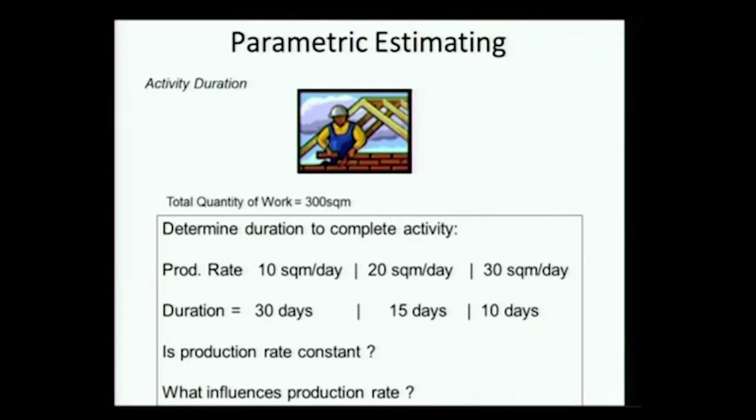There are so many factors which influence production. And one thing we have not discussed, being masonry, is what are the work factors, what are the materials. So if I use block work versus bricks, what is my production? If I am working at height versus ground level, what is my production? So the point I am trying to make here is there are a number of factors which make this kind of estimating a challenge.